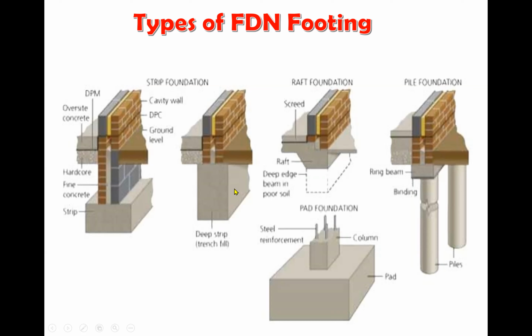Because of all of that uneven movement and the soil moving, you don't want settlement to take place and then the foundation shift. So you want more friction against the side on both sides as well as your end bearing. So we tend to use deep strip in a clay type soil.